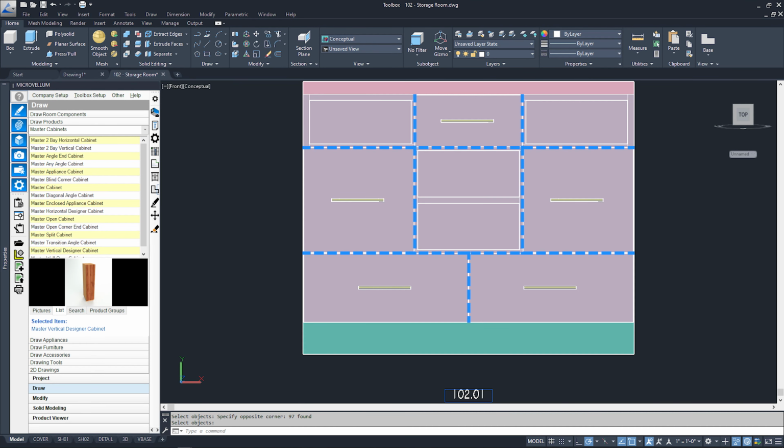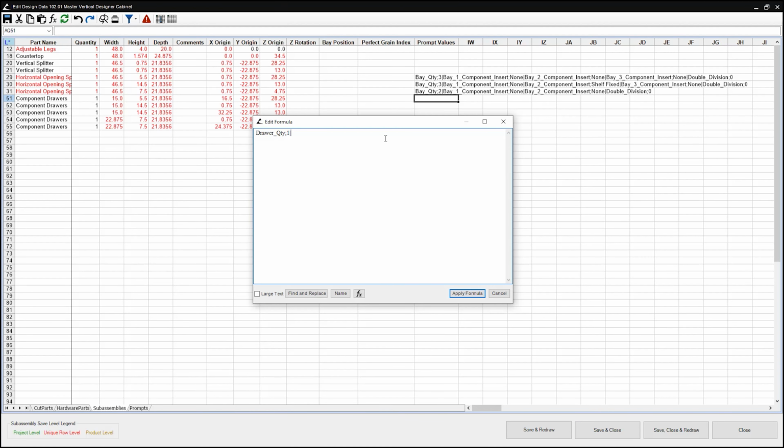The rest of the changes will be in regard to the overlays. To keep our sight lines clean, we need to adjust some of those overlays. So first, we'll change the value of custom overlays to 1. Then set the left full overlay value to 0. This is turned on by default. Next, we'll set the left half overlay to 1. We'll make the same changes to the right overlay options and bottom overlay options.